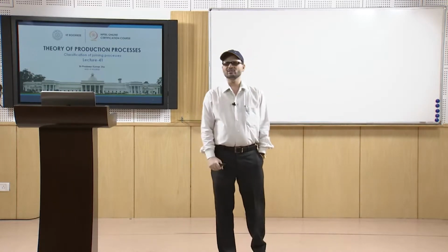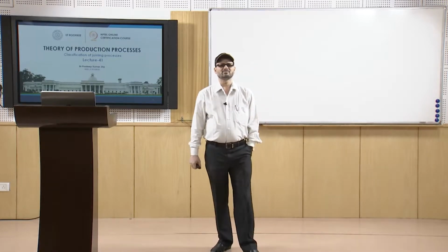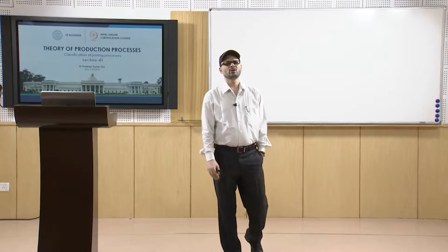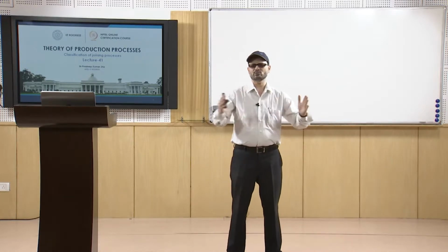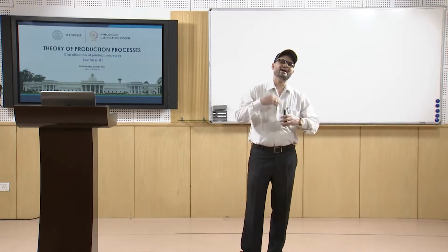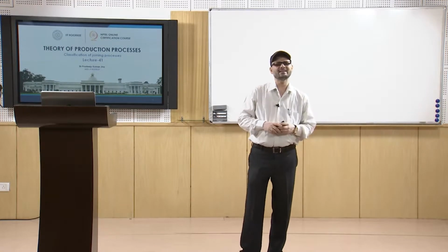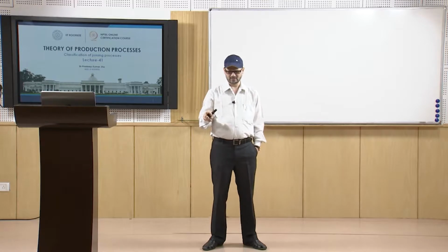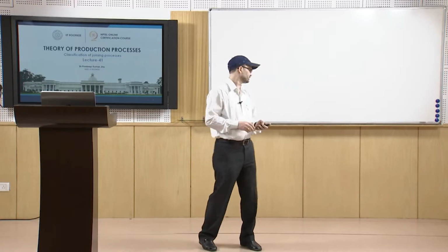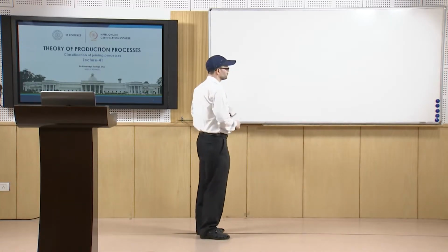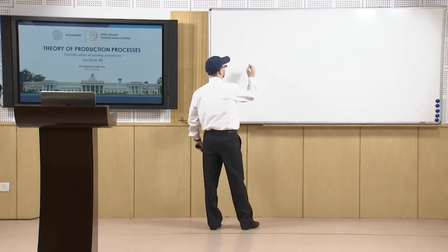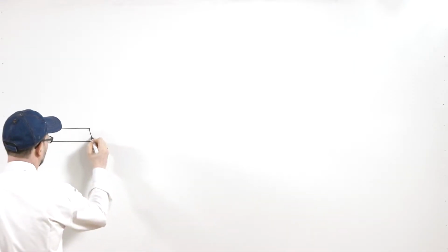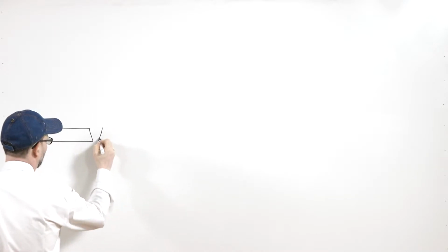homogeneous. Now, in the homogeneous, the filler material which is used for joining the two parent materials has the same composition as the parent material. When you are joining two plates, whenever we do the welding, you have two plates and then we try to weld them like this.